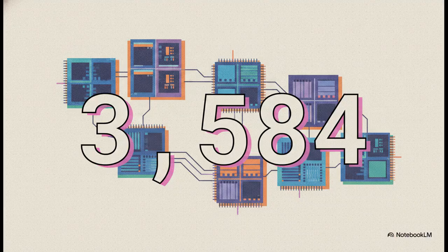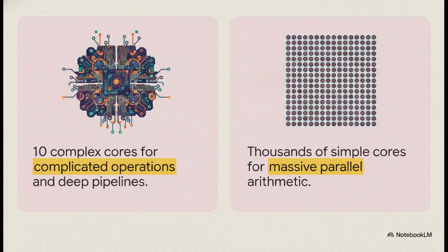If the CPU is the brain, the graphics processing unit is undeniably the heavy lifter. Inside the GPU's die, you will find an astounding 11.8 billion transistors, but they're arranged way differently than in the CPU. They actually form a staggering 3,584 simpler processing cores, which are organized into 28 streaming multiprocessors. This right here brilliantly illustrates the classic difference between brain and muscle.